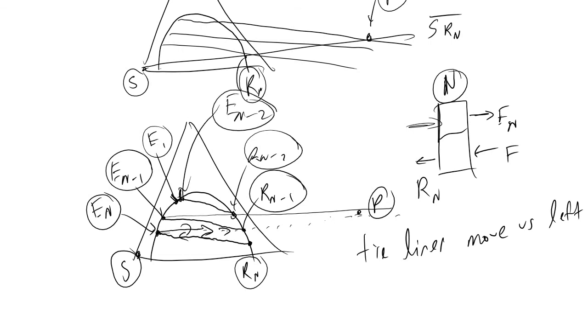And what we'll note now is that E sub n minus 2 has a greater mass fraction of our solute A, because this is our solute vertex, than our required E1 term has, and therefore we can stop adding stages into our liquid-liquid extractor.